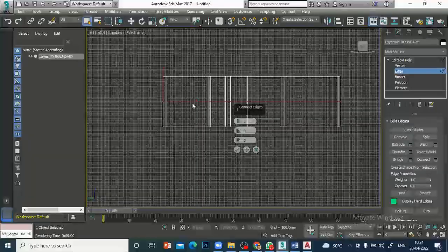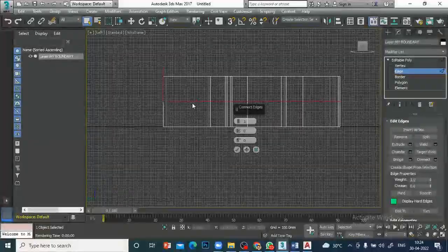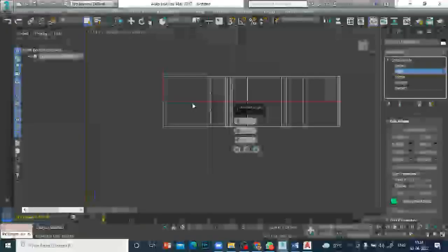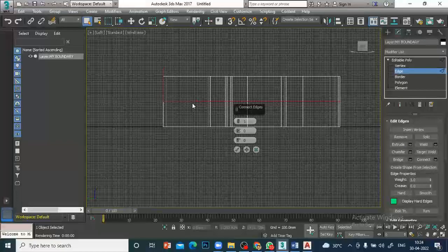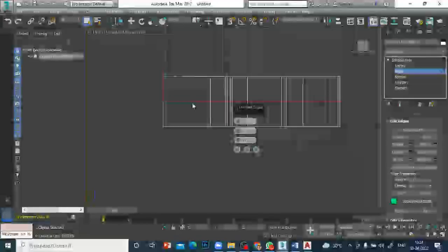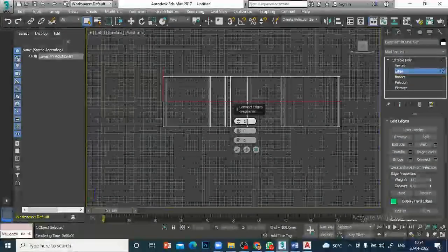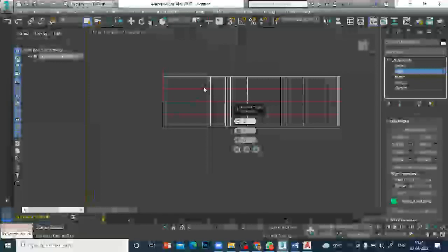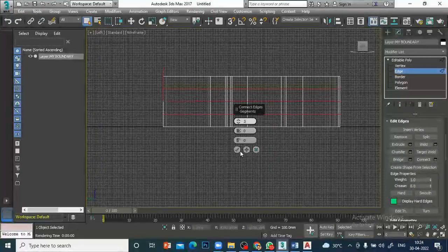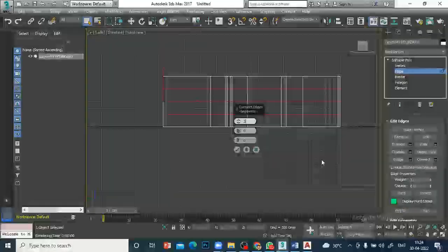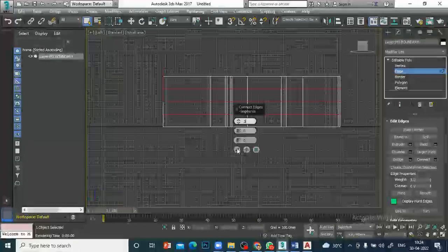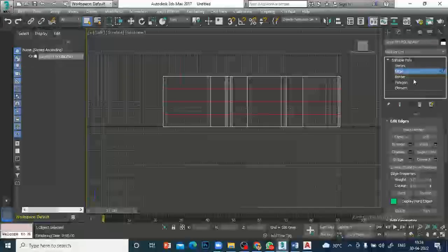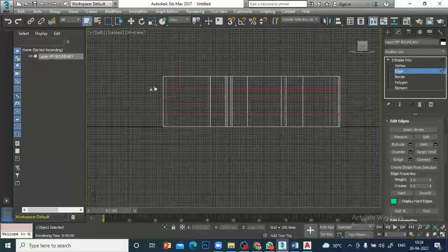Then we want one other plane for the sill level, another for the lintel level. So you want 3 cutting planes. One is for the skirting, one is for the sill, one is for the lintel. So I will type here 3. So 3 planes he created. And I will say tick mark. Tick means accept. If you just go out, then it will not work. So click this tick. Click. And it created the planes there, all together.